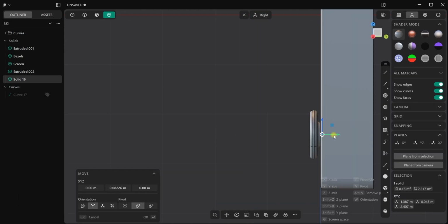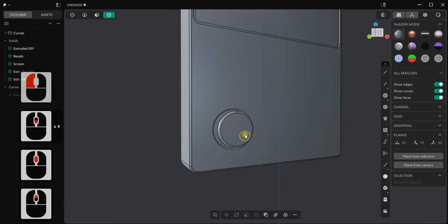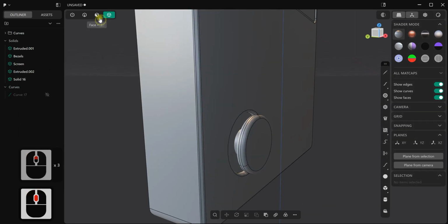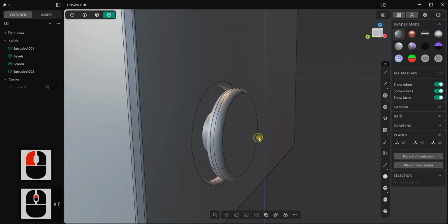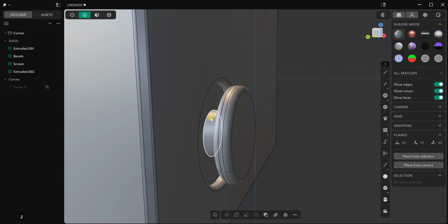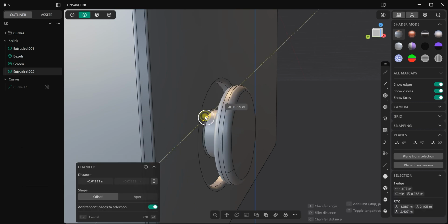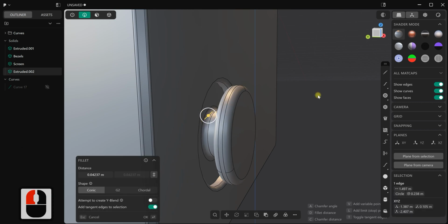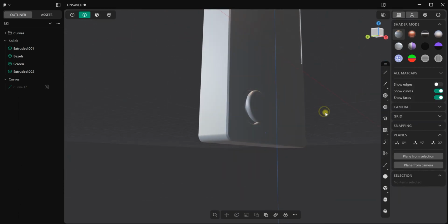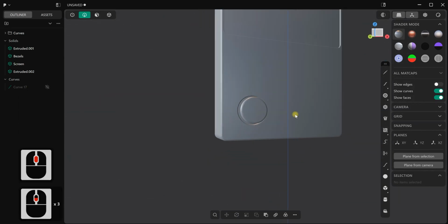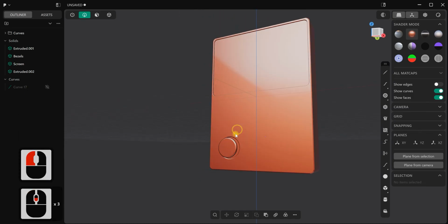In solid, adjust a little bit. Okay, in solid mode, select our joystick and extrude it solid by clicking and holding Shift. Press Q and Q again to unionize our solids and create one. It turned blue. OK to confirm. In edge mode, select this edge and give a fillet. Right click to confirm. And let's check the results from different sides. It looks awesome and exactly what we needed.